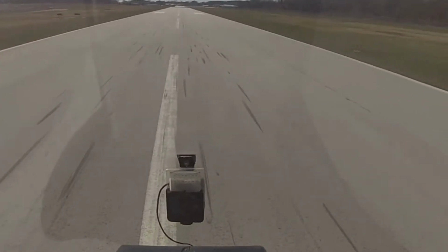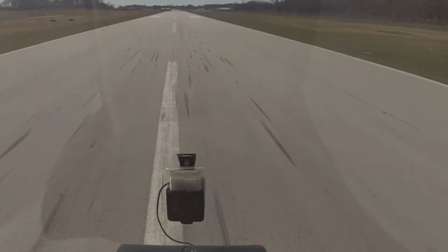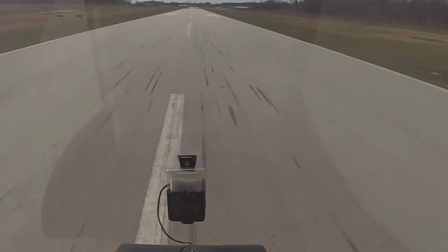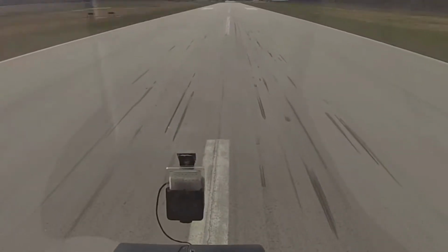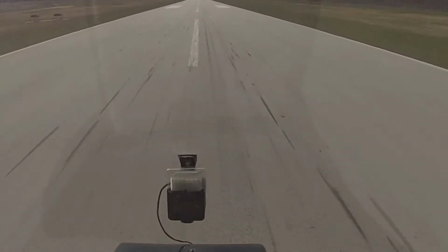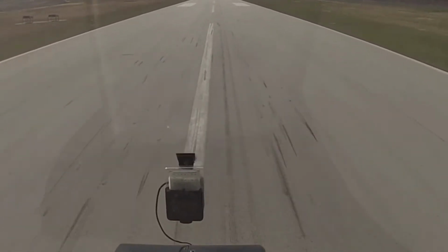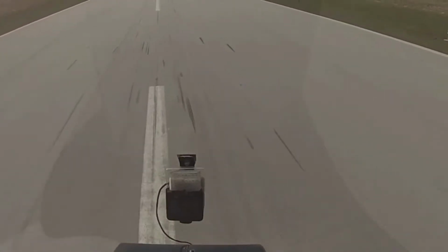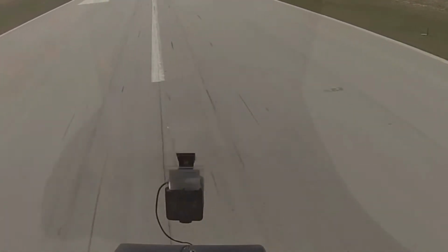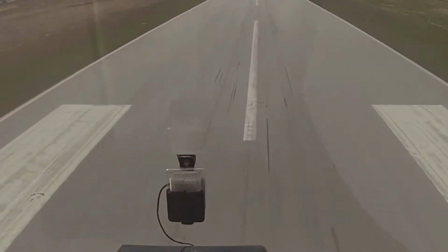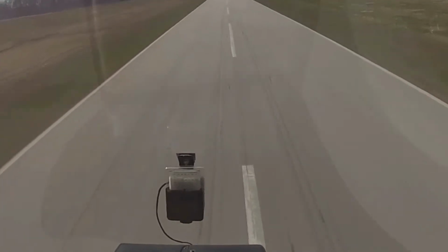So we're keeping it close to the ground, keeping the nose straight, and we're just going to start moving forward very gently. If the engine quits, all we've got to do is cushion the landing, add some right pedal, and we'll be just fine. So staying in this takeoff profile, we're just going to stay close to the ground, building a little more speed, a little more speed, a little more speed. Airspeed's right around 30 or 35, hitting 40, so now we're going to start climbing up. This is helping us stay out of that shaded area.